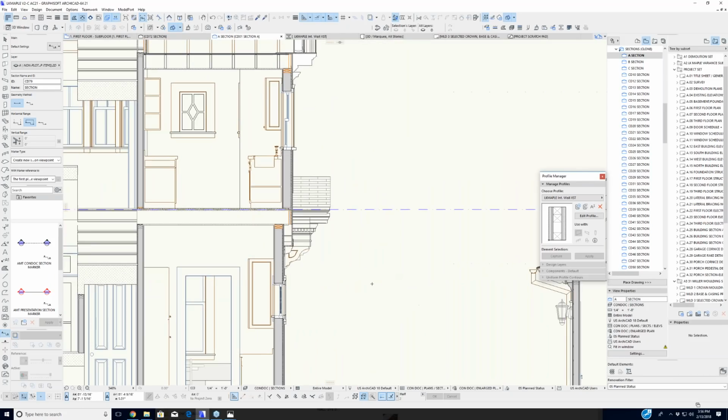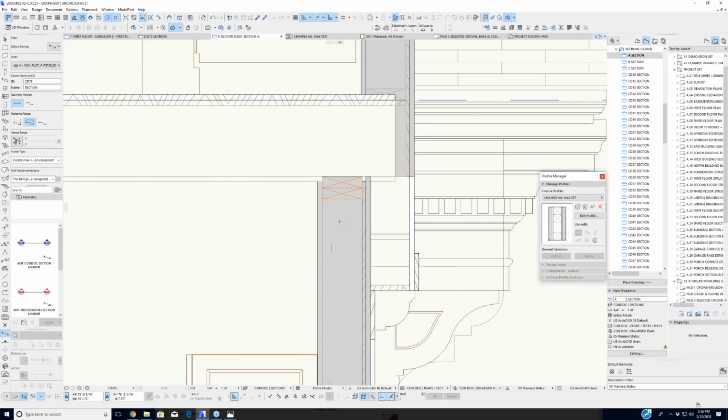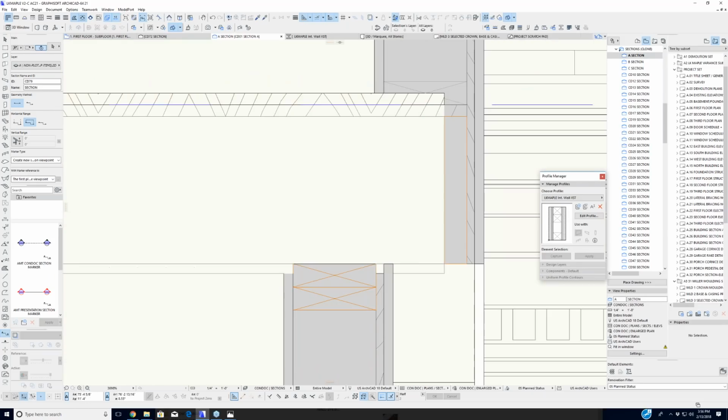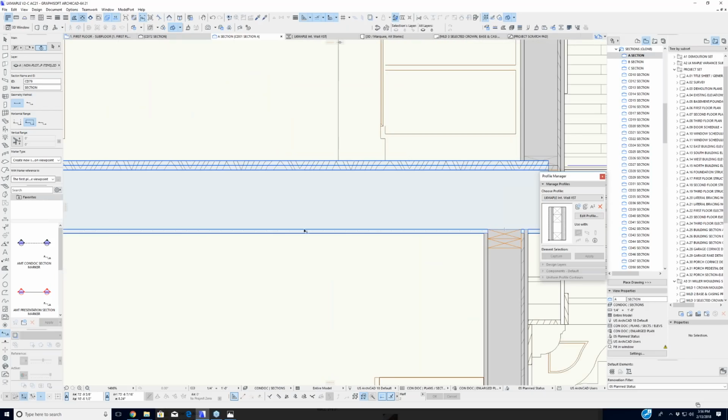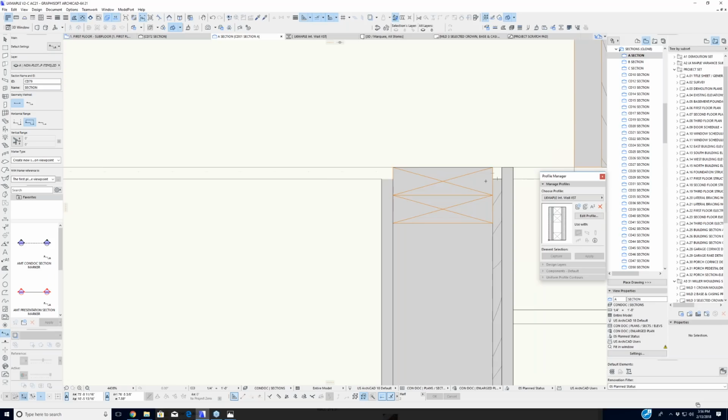So here's a live section, and here's where it's showing up shaded, what's new, and then you can see this is the floor, and there you can see a version of wood. This is just a standard 2x10. This is the new section. This would be 5/8 sheetrock. That 5/8 sheetrock gets automatically cut out of that top plate because that top plate in my complex profile is a higher building material priority than the drywall.